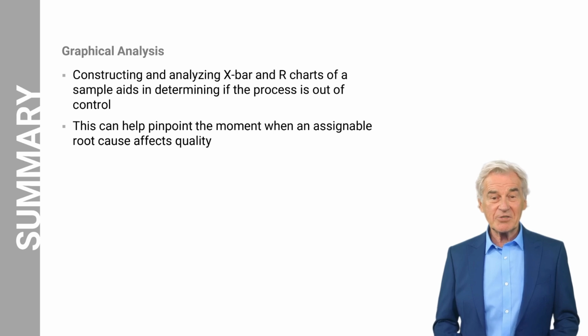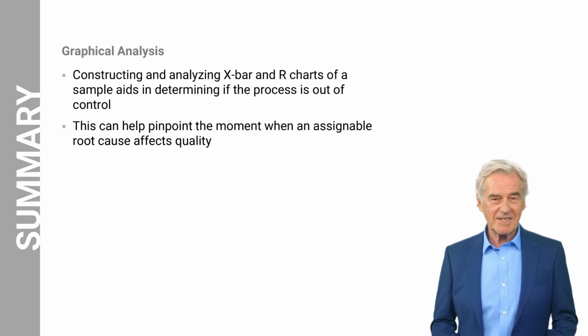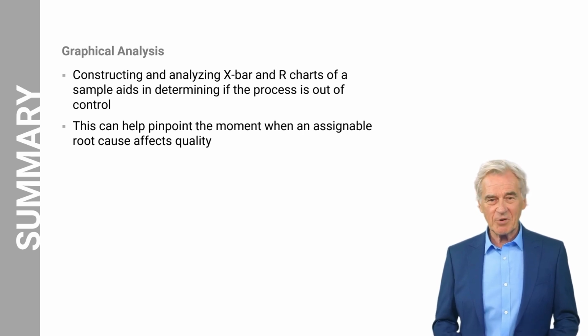In summary, constructing and analyzing X-bar and R charts aids in determining if a process is out of control and can help pinpoint the root cause of the problem. These tools can be used to improve the overall quality of your processes and, in turn, your company.